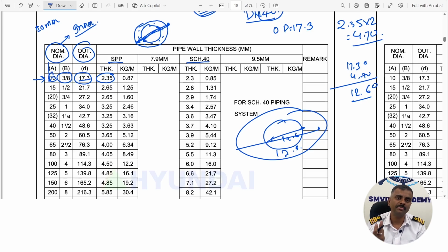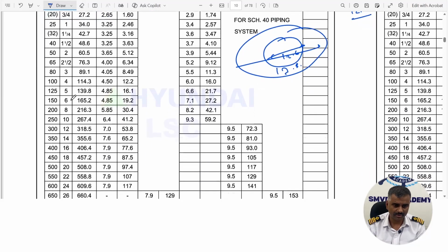It is just for the manufacturer to know what pipe size has been ordered, what is the nominal dia. So nominal dia is a theoretical number, a name for the pipe size. Similarly nominal dias like 15; this chart all goes into mm. This is what I wanted to discuss.